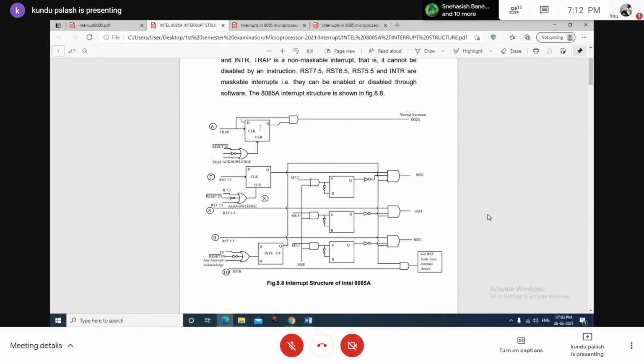In fact, there is a hardware situation: the microprocessor is excited by a 5-volt DC power supply, and when there is a loss of power, that means power interruption, what will happen? The voltage will drop down and it will take some time. But there is hardware circuitry which will sense the power failure or the drooping of this power.